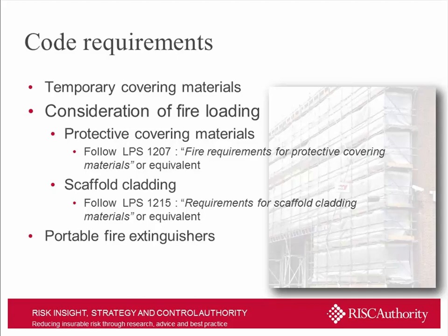Introducing some form of plastic into that scenario is obviously going to increase the fire load quite significantly. And so there are specific requirements in the code for use of protective covering materials which are third-party certified to specific standards. I've listed the 2 LPS documents there, which I'm sure you're familiar with, but there are similar standards produced by Exova Warrington that provide a similar degree of protection.